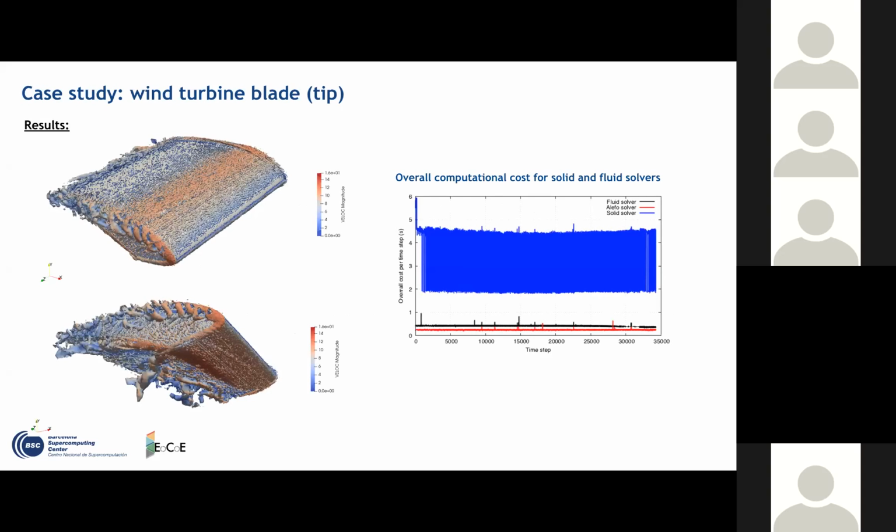So if we had these kinds of times, it would mean that the full fluid-structure simulation would take much more than if we only do the fluid. What we see here is approximately 0.5 seconds for the fluid and close to 5 for the solid, so perhaps not 10 times, but 5 times more.